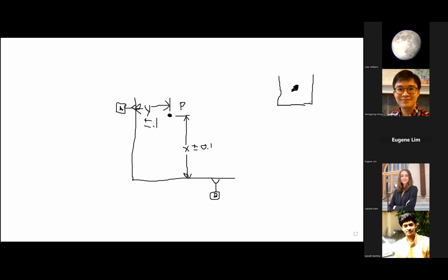Similar for relative to B, we've got another two lines, so we can move up 0.1 and we can move down 0.1. And so we've got this whole box of room to put this point based on the tolerances. So plus minus 0.1 in either direction.